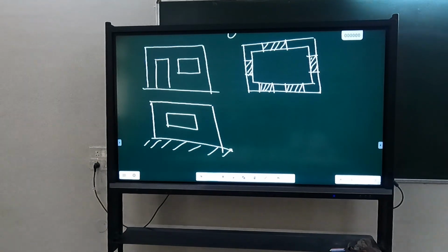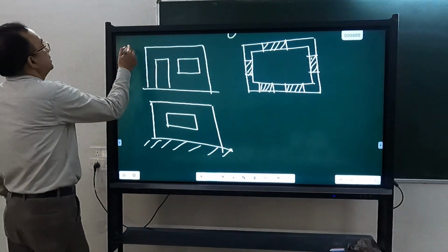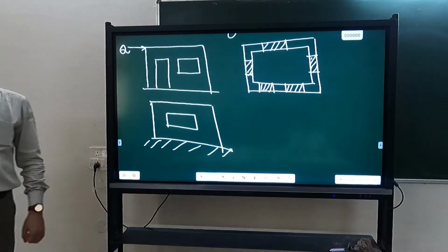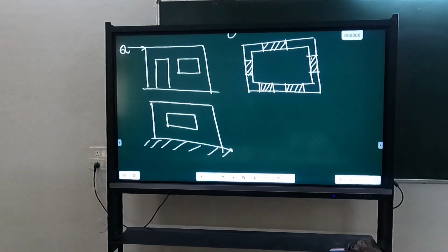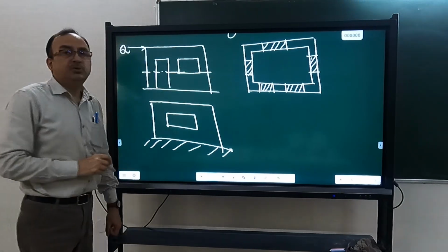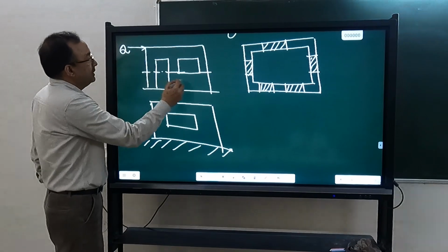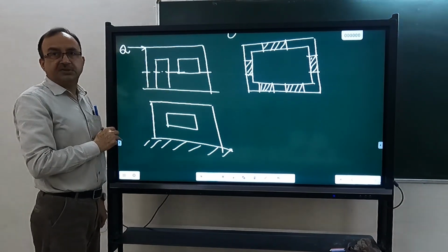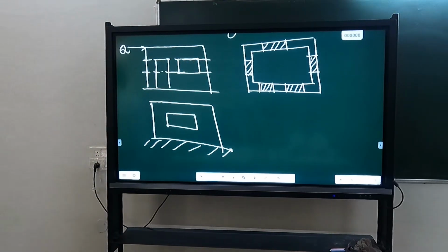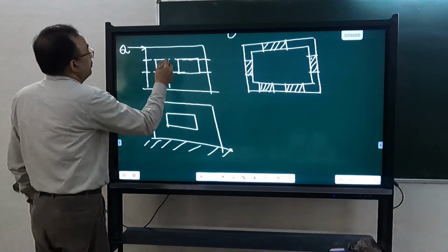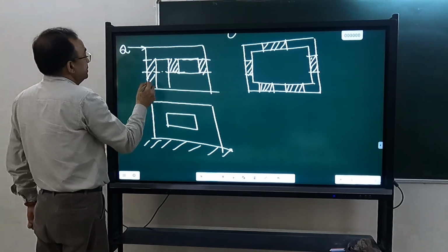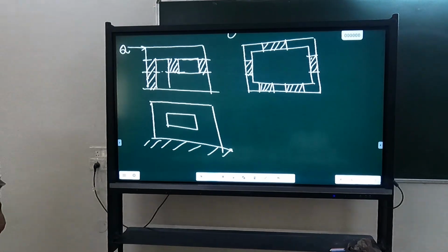Okay, and in your masonry course you are calculating that if you apply a force Q here, how much will be the force in different piers. The most critical section is this one. Why this is most critical? Because below this you can see that larger cross section is available. Above this also larger cross section is available. So most of your deformations and failures will occur here. These we call piers.